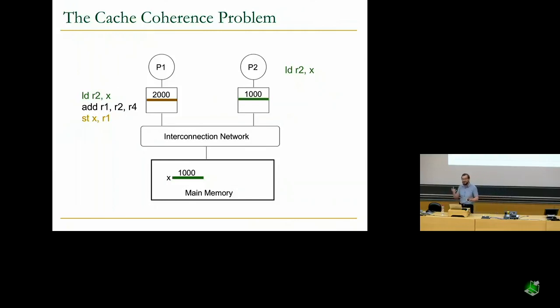And this was actually one of the key design choices that I believe IBM made in their Cell Broadband Engine, which went into the PlayStations. They said, okay, coherence, we're not going to support it in our caches. We're going to have the programmer manage it. And this thing was a beast to program. As a result, they didn't continue it over time. So usually, if you get rid of support that's there for the programmer, you may actually lose. Because if you remember, there are a lot of programmers, and if your hardware is not used by those programmers, then you have a problem.